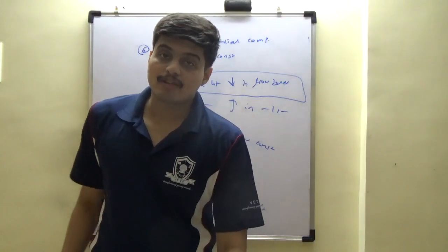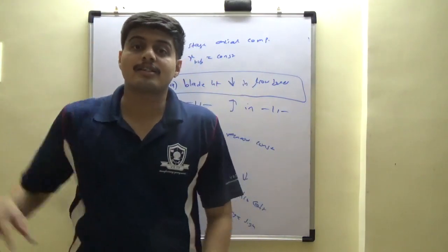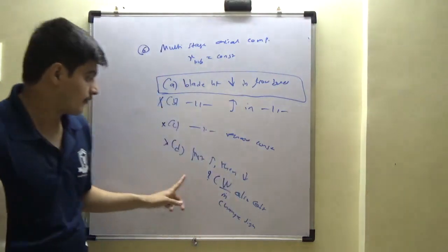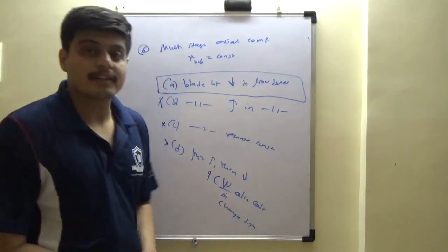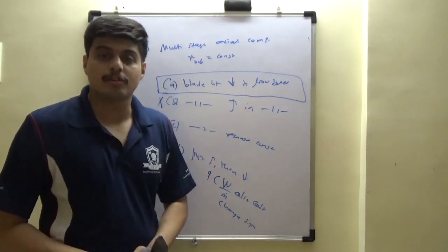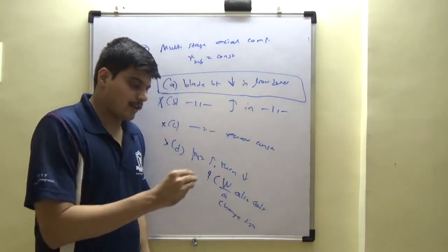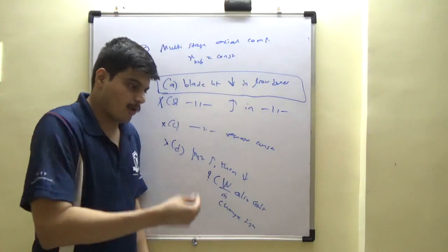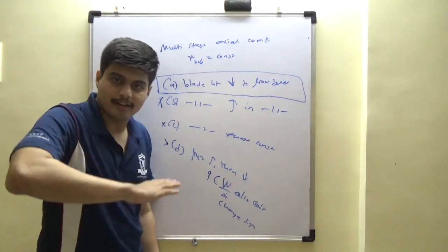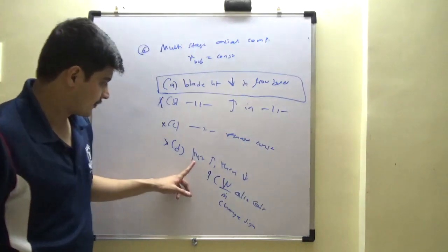Transfer of work has to be smooth and continuous because this is directionally asymmetric. See the mathematical reasoning. So an increasing-then-decreasing function will not satisfy this case. It has to be a monotonous function. Right? That's the reasoning I am doing. Physically, I cannot keep adding some energy and then removing some energy. I have to always incrementally add some energy, or the increment should be zero. I cannot start removing the energy from the fluid.